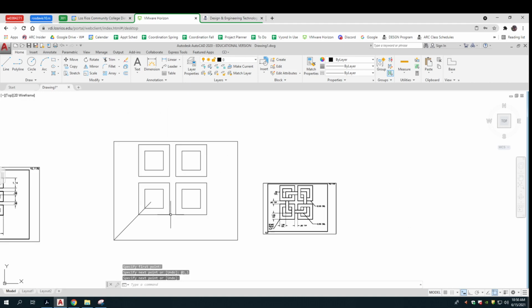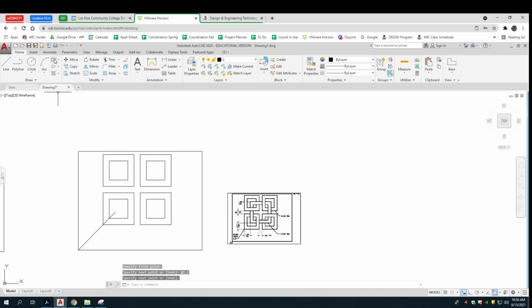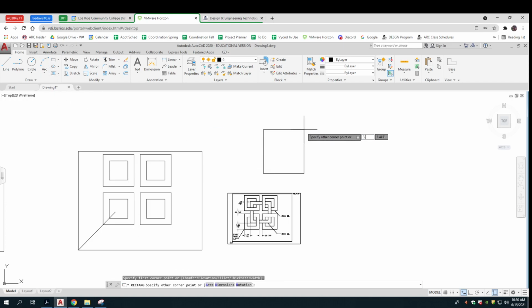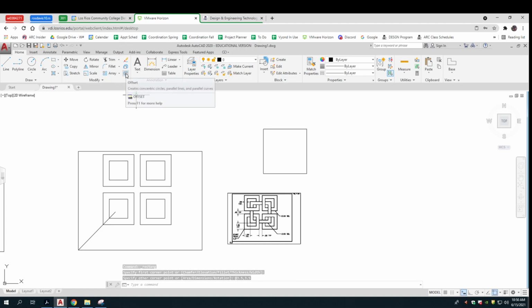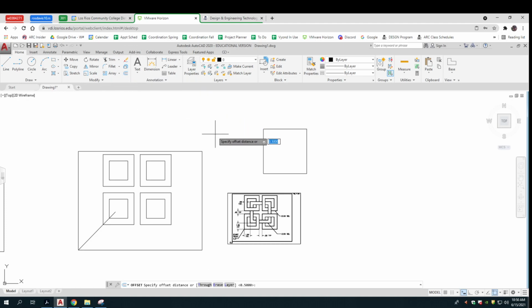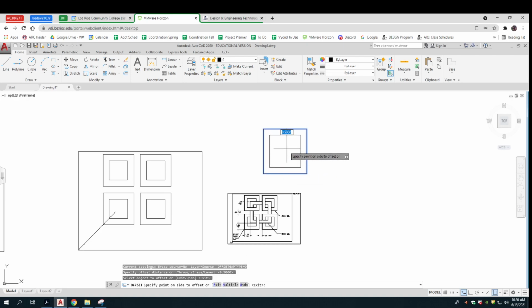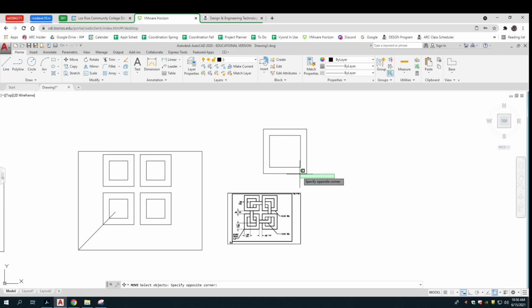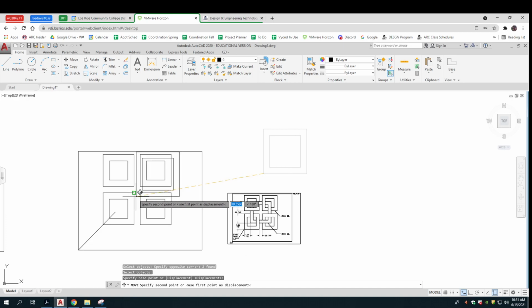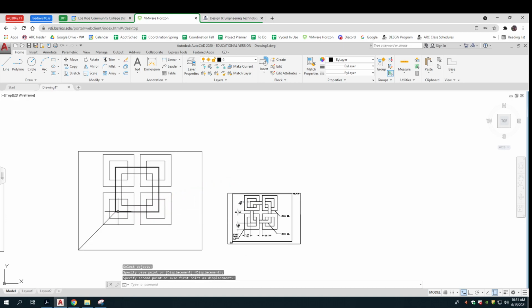That's where it's going to go. Now I can draw that other square anywhere. 3.5, comma 3.5. You did rectangles last week with an offset of 0.5. It's already in there. Enter and take that shape and move it in. And now I have the move command. So I drew it somewhere, and I'm going to move it so that this bottom corner is at the end of the line.